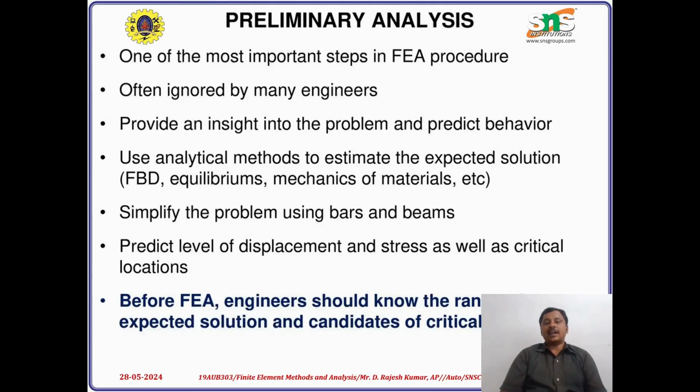Preliminary analysis is one of the most important steps in finite element analysis. It is often ignored by many engineers, but it provides insight into the problem and predicts the behavior of the output results. In this stage, we use analytical methods to estimate the expected solution. For example, boundary conditions, free body diagrams, equilibrium, and mechanics of materials are considered.